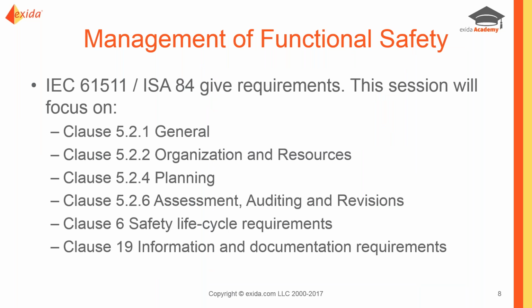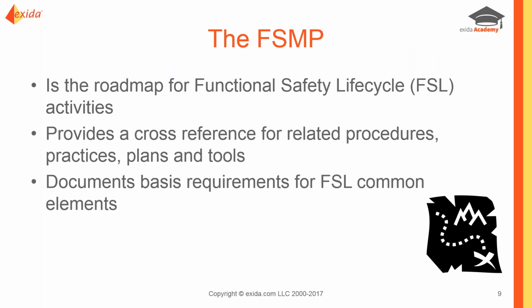IEC 61511 has several clauses that list the requirements, and these are the ones that we are going to talk about: the general requirements, how we organize and plan, how we address the plan for the assessment and the auditing. Clause 6 gives us some specific guidelines on how that plan ought to be laid out. And of course, in the course of this activity, there are a lot of documents that are source input documents, and a lot of documents that we generate. So we need to make sure that documentation is functional in the end.